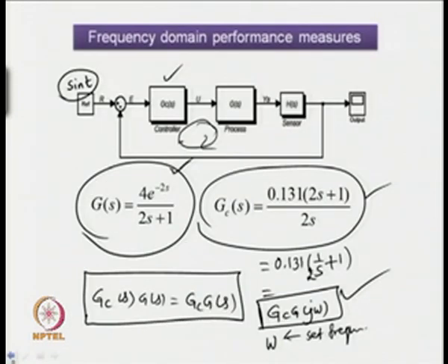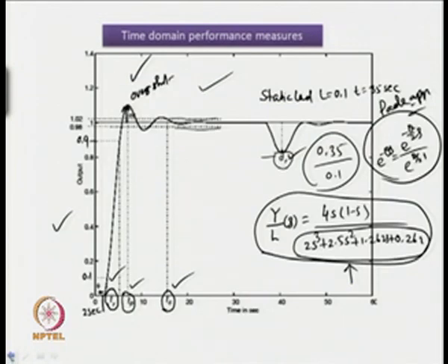That can be explained with the help of the time response of a closed loop system. So, this is one peak, and the magnitude of peak with reference to the reference input can be given as, suppose, P 1, and we have got another peak over here, P 2. So, the ratio between P 1 and P 2 gives us the decay ratio.